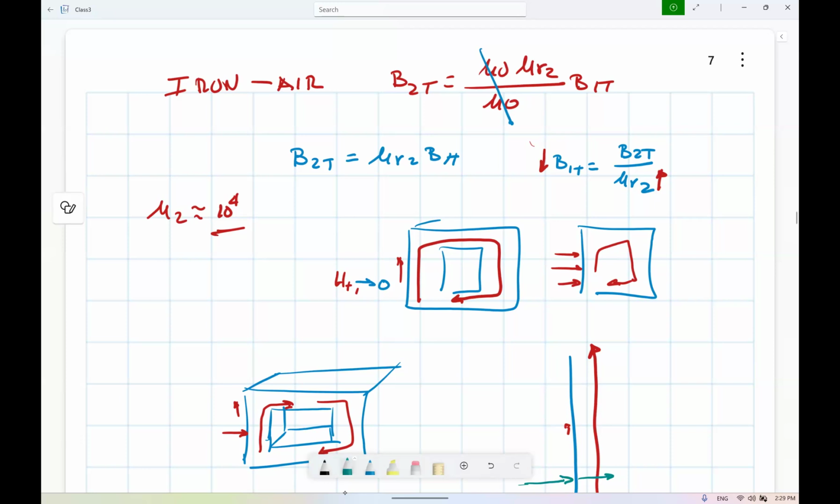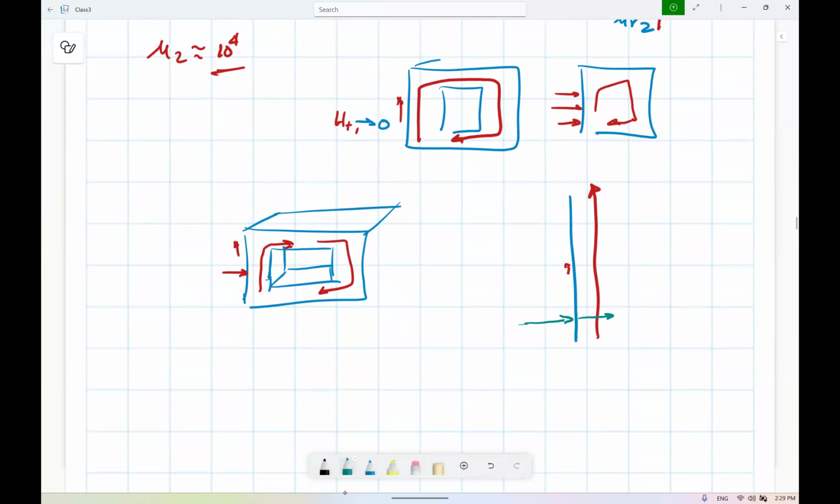Now, please, don't rely too much on the streamlines. The streamlines in COMSOL, I think they have made them better, but they used to be very bad. So use arrow plots. ANSYS does a very good job with the streamlines, and probably now COMSOL does it right. I don't know. But I prefer to use arrows proportional to the magnitude, and lots of little arrows so that you can almost see the streamlines.